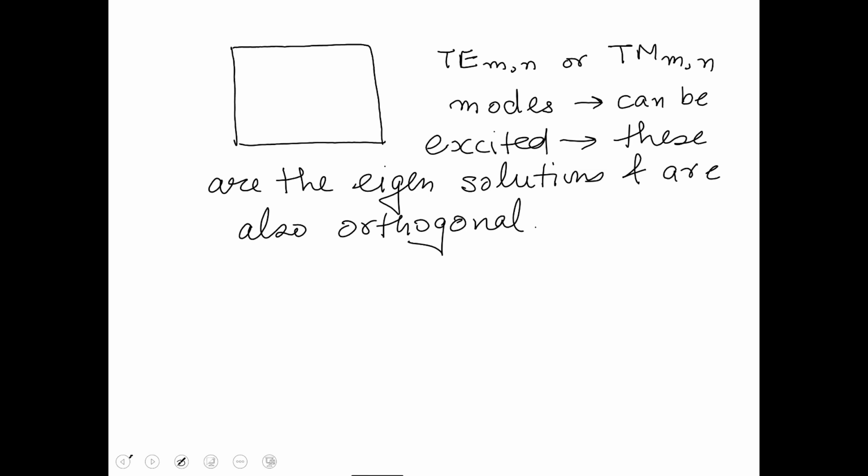The modes are orthogonal. If I have a mode TE10 or TE31, I can't represent that mode as a summation of some modes. So effectively, if I have a mode which is, let's say, TE31, this is not going to be TE30 plus TE01. It's not going to be that. Each solution is a unique solution of its own, and I can't represent that solution as a summation of